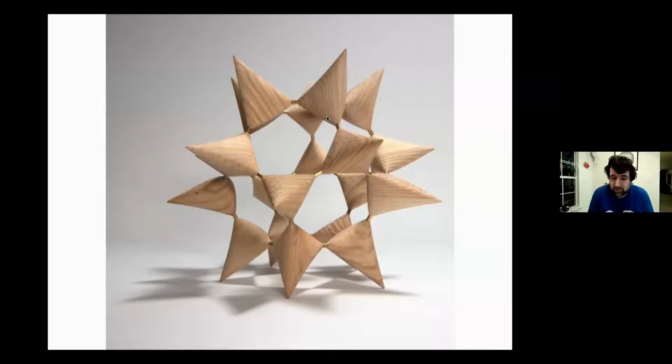So we took that mathematical surface, which is a bunch of equations. Those equations give you the surface, they don't give you the paths. But from those equations, you can get a point, any point on that surface, and you can draw curves on that surface. And then at each of those points, you can work out what the normal direction to the surface is. In other words, what direction do I want to have my flat-ended tool so it carves that piece of the surface really nicely?